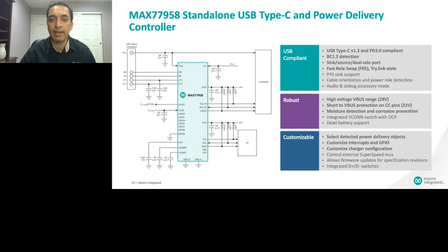We have non-volatile memory built into the IC, which allows you to configure the device to operate according to the needs of the application in your factory. You can configure it in your factory during your final test and have that in the non-volatile memory for the lifetime of the product. And you can also update that non-volatile memory in the field if needed in the future.